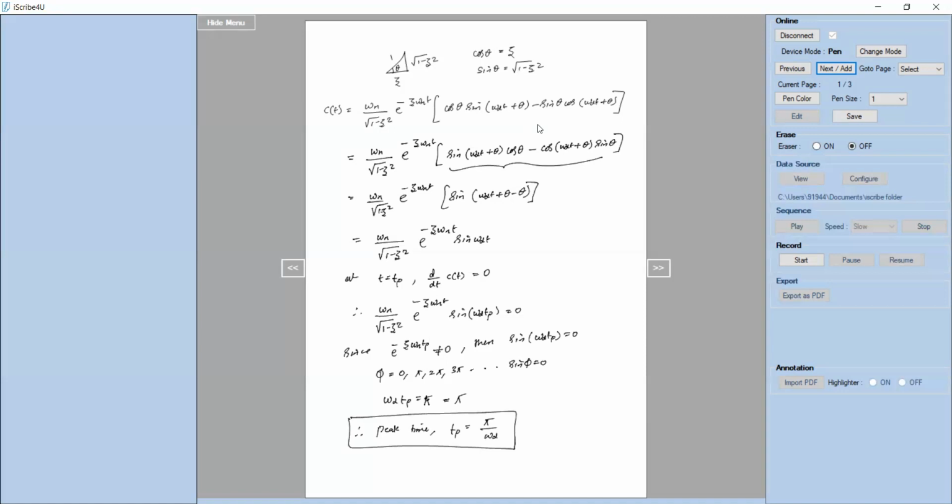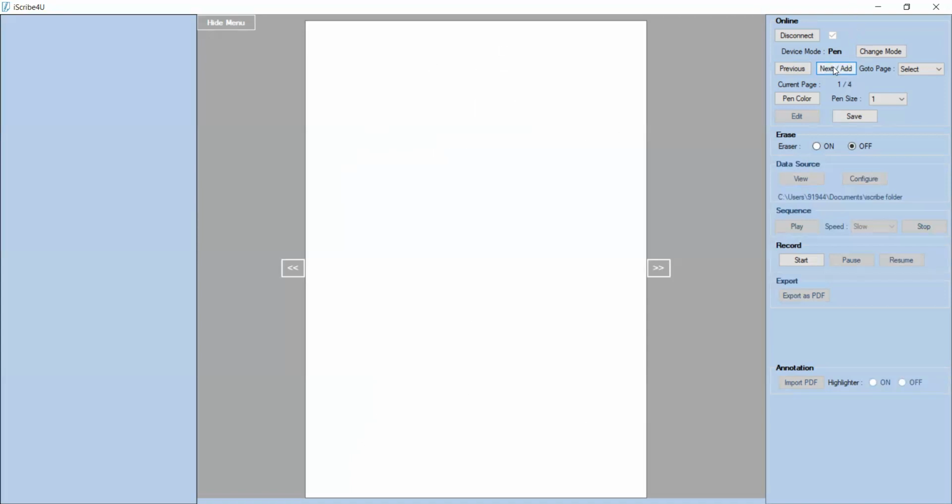Okay, and we know that omega d is equal to omega n square root of 1 minus zeta square. So I can write Tp as pi divided by omega n square root of 1 minus zeta square. I can always use this equation also. Okay, so this is about the time tp. Next we will go to the peak overshoot. I'll go with the peak overshoot expression.